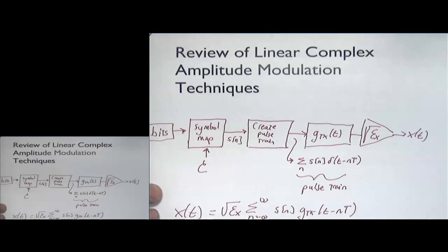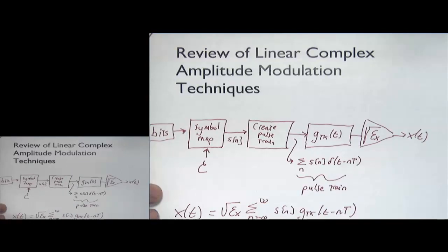And then towards the end of this lecture, we're going to talk about how this signal is impaired potentially by additive white Gaussian noise, and then how we detect the symbols from that. Later, in a couple lectures, we'll talk about how to replace this weird operation here with something that you could implement in a DSP, and that's what you'll actually implement in the lab. So we'll replace this in a little while based on some ideas from multi-rate signal processing. So that's where we're going right now.